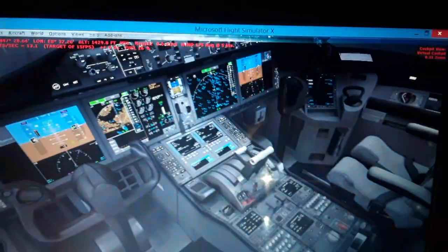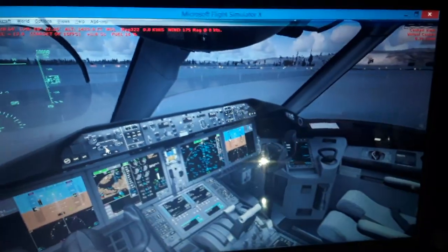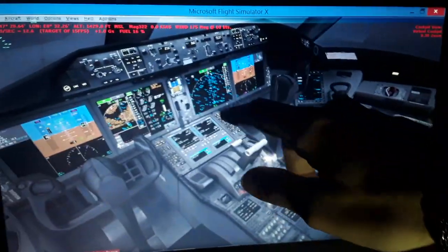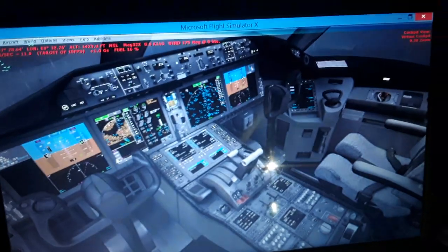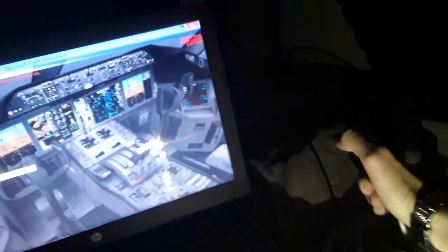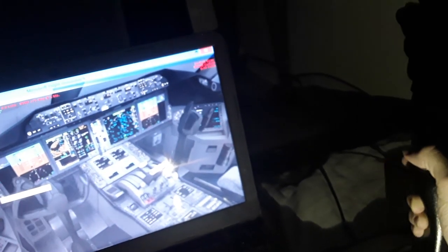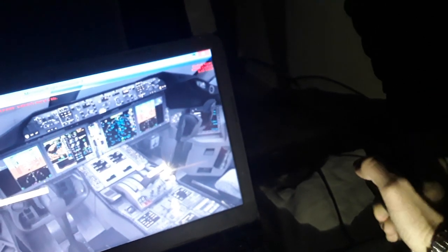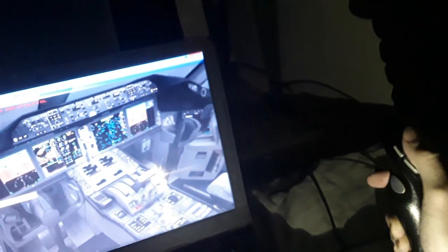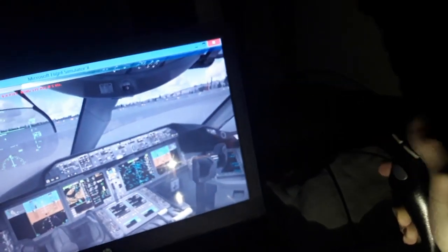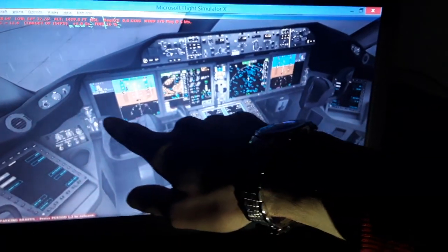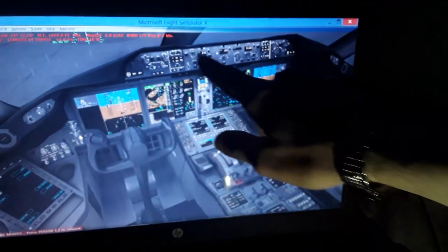So you have the autopilot here and auto throttle, and also the auto throttle over here and the flight director. So you have the fly-by-wire system of the aircraft, and this is a fly-by-wire aircraft. It has an auto trim function by itself using its flight management computer and flight control computer, so it can balance itself on its own. You can also use the trim switch to balance it yourself. This is the manual only trim channel. So this is the automatic.